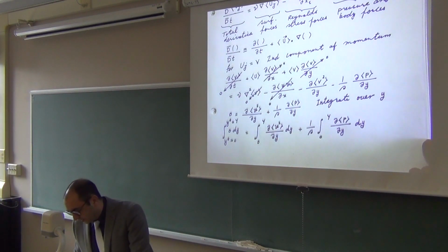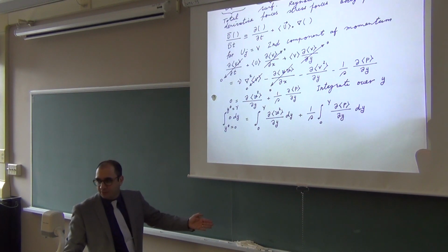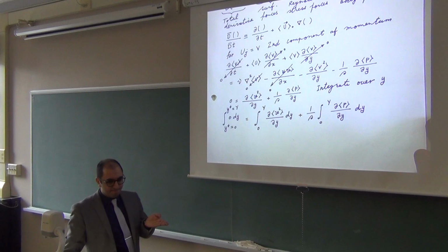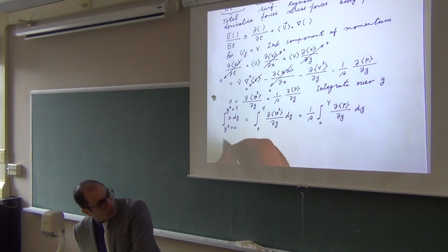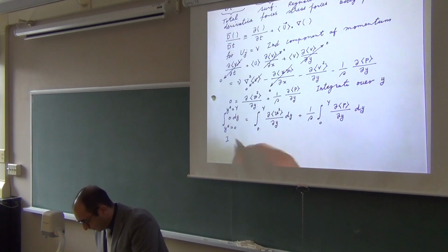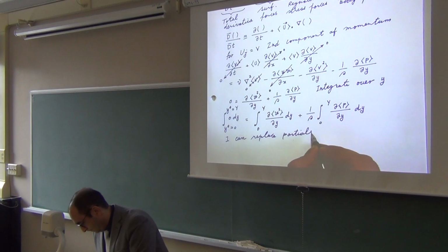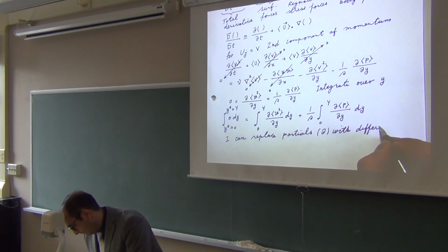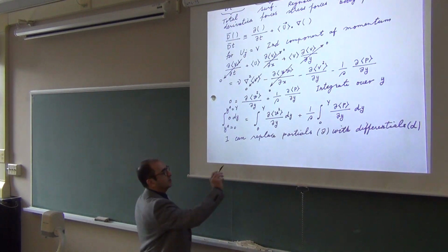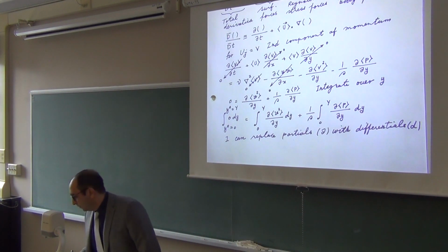Now it looks like the only variation is variation normal to the wall. In other words, there was no variation in the z direction either because of homogeneity and symmetry, and a lot of the components did not vary in the x direction along the flow. So really the only meaningful variation for most of these variables is in y. So I can replace the partial symbols with differential symbols, d. I mean, this would be d v squared dy or dp dy. And it simplifies extremely if you do that.